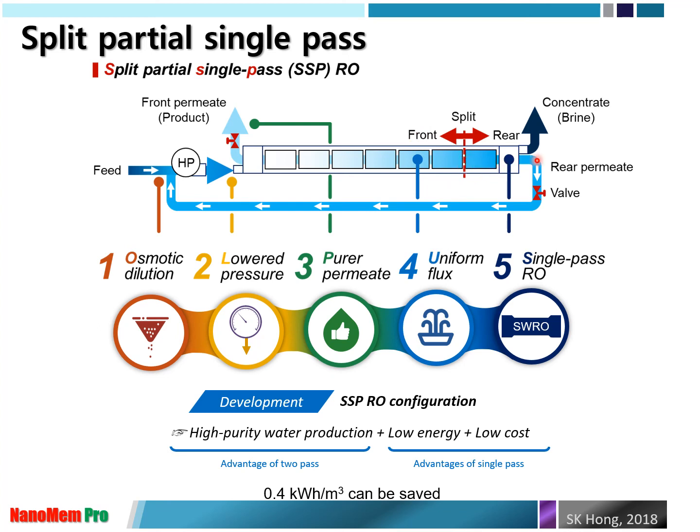If you collect your permeate at the end of your RO module and send it to the feed water side, this seawater keeps increasing in salinity, which means the permeate quality has very high salinity, and therefore if you mix it with the front module, your overall water quality is not as good as your initially collected module permeate.